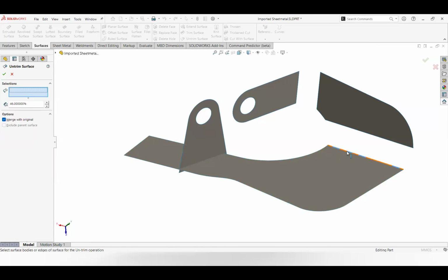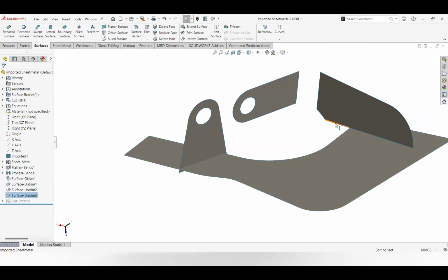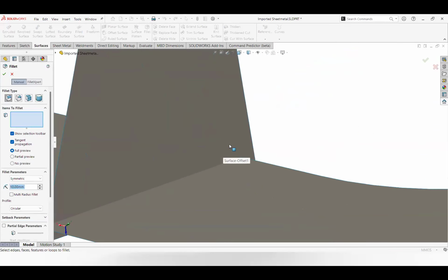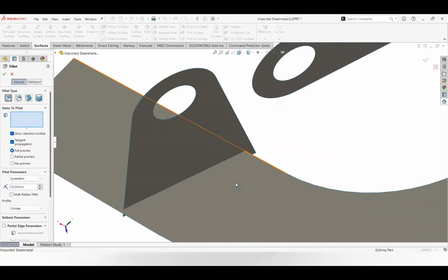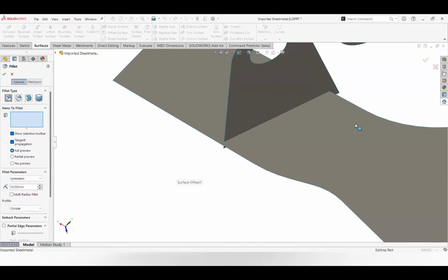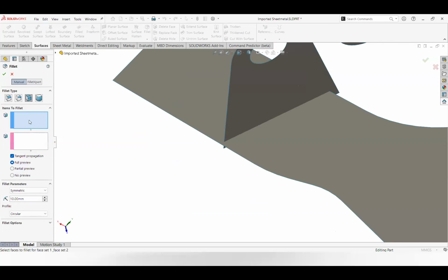because every surface body is typically rectangular in the background. And it looks good. I'm just using the repeat command with enter. Okay, so now what? Well, we can use some fillets, because a face fillet's really handy here, especially where these are not going to line up nicely. I can't trim these to each other. You can only trim surfaces when they actually completely cut through each other. And those don't, but I'm going to make it sheet metal anyway.